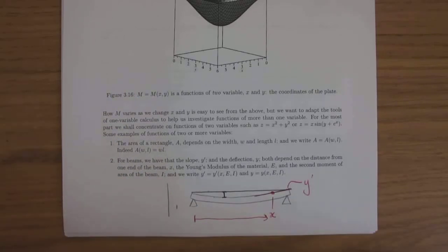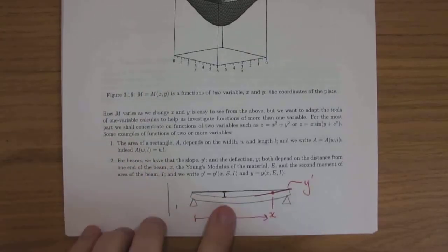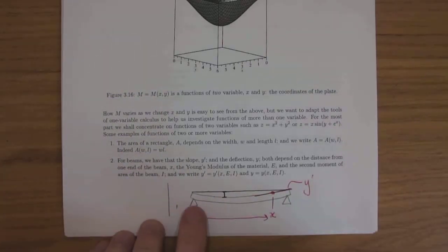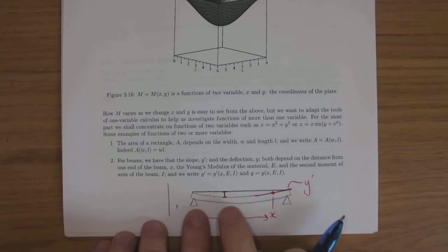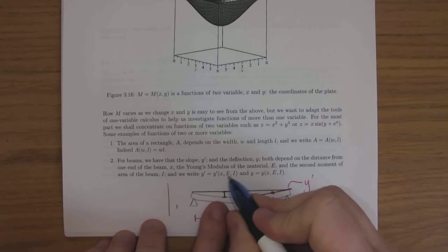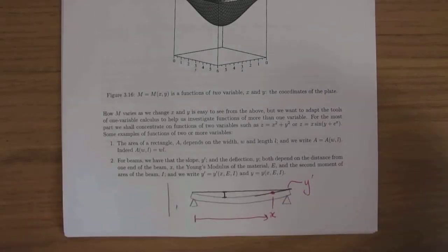Now, in general, you think of both the slope here and the deflection as functions of a single variable, the distance along the beam, but you could think of them as a function of several variables. The other variables being basically what the beam is made out of, and that's the material. That's where the E comes in. It's the Young's modulus. So how stiff is the material of the beam, and I is the cross section of the beam. So it's kind of saying that, fix the length here and have different beams, the deflection depends at each point on how far along the beam you are, the material that the beam is made out of, and the cross section, something like this.